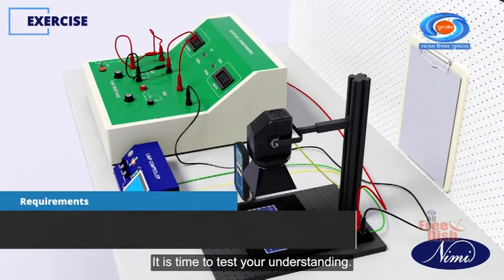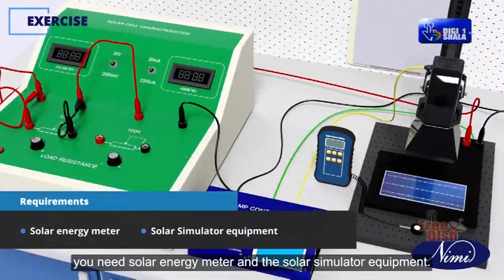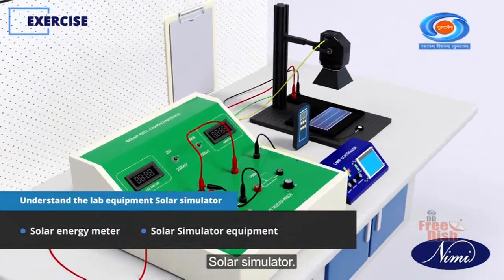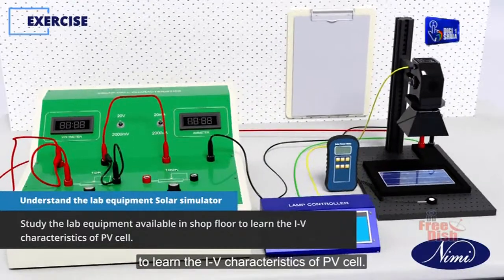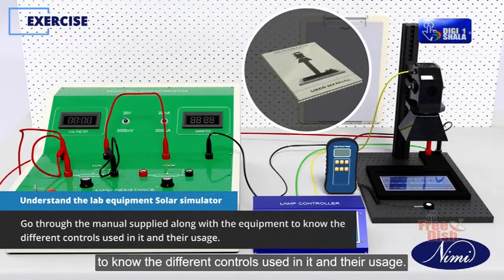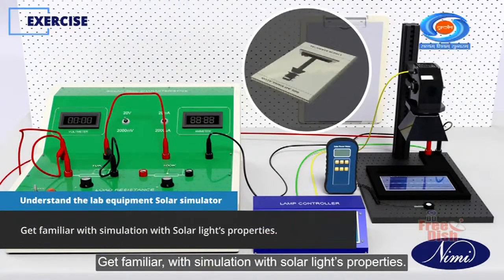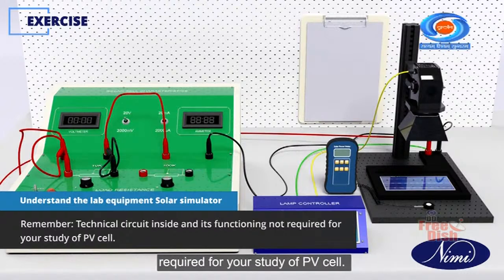It is time to test your understanding. To perform the task, you need a solar energy meter and the solar simulator equipment. Your first task is to understand the lab equipment, the solar simulator. Study the lab equipment available in the shop floor to learn the IV characteristics of a PV cell. Go through the manual supplied along with the equipment to know the different controls used in it and their usage. Learn the do's and don'ts. Get familiar with simulation of solar light properties. Remember, the technical circuit inside and its functioning is not required for your study of the PV cell.